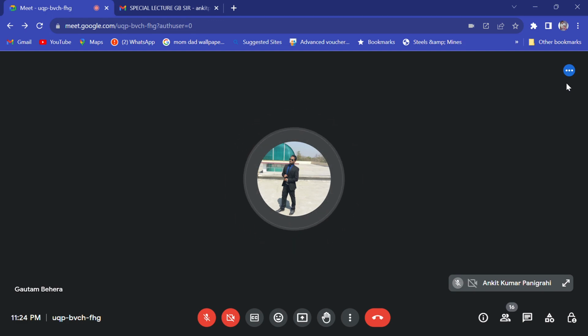Now the point is, how to recover chromium. Suppose you want to make 18:8 stainless steel, but since your chromium has gone to the slag phase, you want to recover it. So how can you recover it? You can convert this slag into neutral slag or basic slag, right? I told you about double slag practice, or that you can convert oxidizing slag to reducing slag, right? So you simply add some amount of aluminium or silicon into the molten steel. What will happen? The silicon and aluminium will react with chromium oxide to form a stable oxide, aluminium oxide, and chromium oxide will reduce to chromium at high temperature. So all the chromium will be recovered into the metallic phase. In this way, you can make stainless steel by using electric arc furnace.